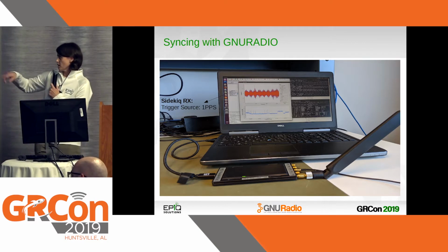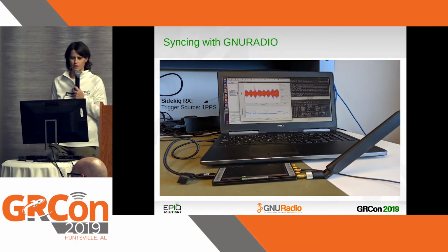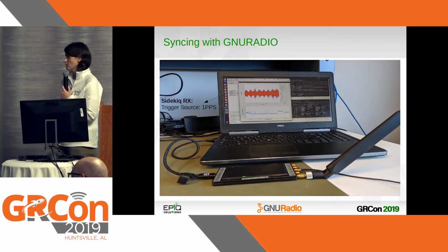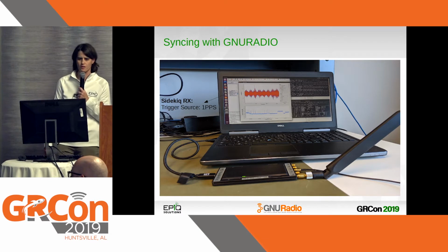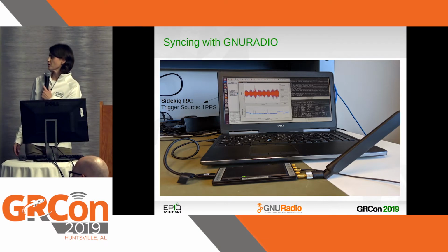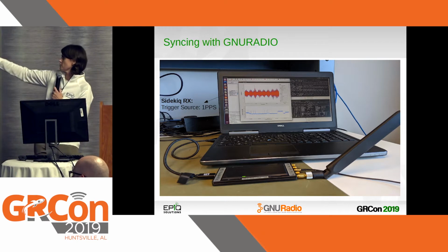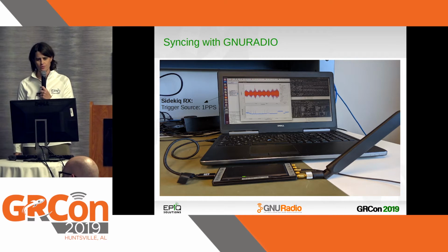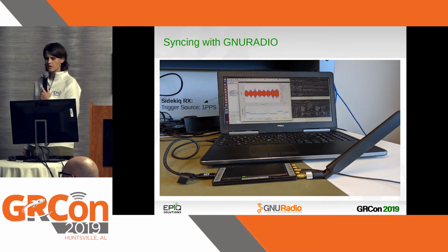On the laptop itself, we have gpsd and gpsmon, which is getting its GPS NMEA stream from the Thunderkick across the Thunderbolt 3 cable. We also have a Sidekick GNU Radio flow graph going, and you can see that we're basically just plotting the time domain and frequency domain of the samples. Again, that's all coming across the Thunderbolt 3 interface.